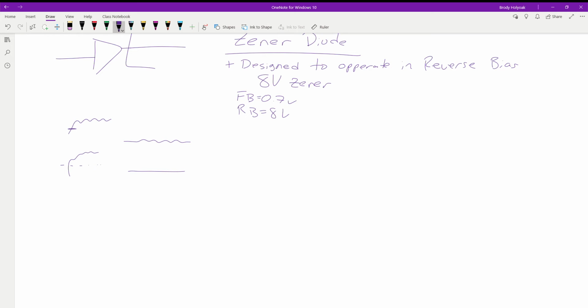All right, so with the Zener diode, we operate it in reverse bias. It has a specific voltage drop that it operates in, and internally it does what it needs to do. It either increases or decreases its internal resistance to maintain this voltage. You get more current, it's going to adjust itself to maintain this 8 volts. That's its whole job, is to maintain whatever value it's rated at. If it doesn't have enough voltage, it's going to grab up every volt it can to keep at that level. So nothing else will get anything.